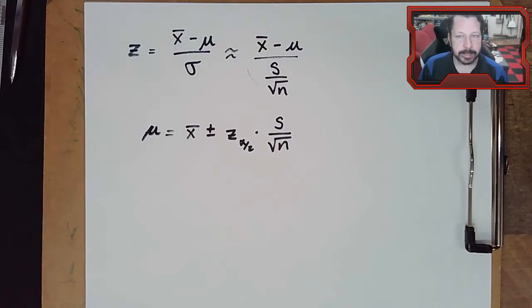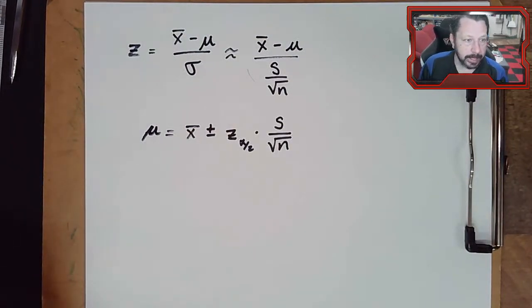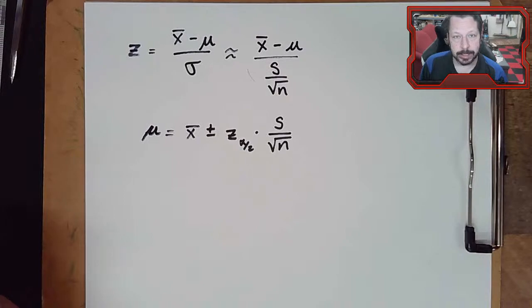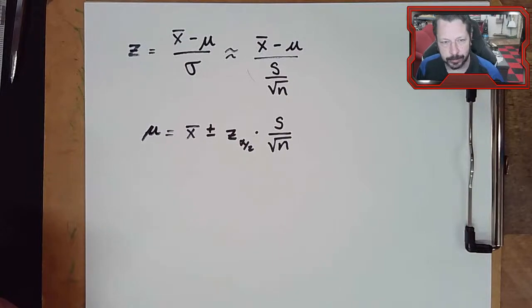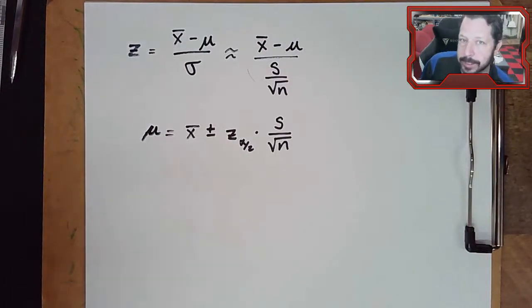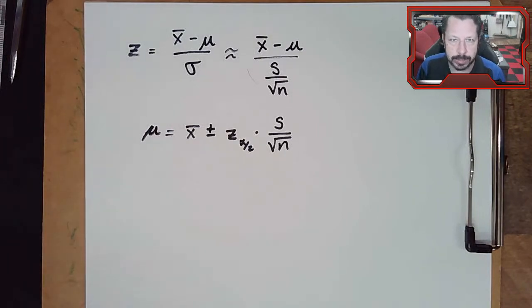All right, so let's get some numbers in there so that it starts to make more sense. Let's say that we have a whole batch of resistors, and you know they have that little tolerance band on them. So sometimes there's no tolerance band, sometimes there's a gold one, sometimes there's I think a silver one. And each one of those means that that resistor was made within some confidence interval that it was actually a 220 ohm resistor, but it might be a 222 ohm resistor or a 219 ohm resistor.